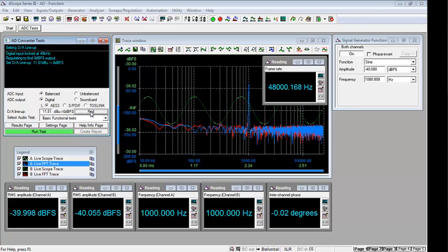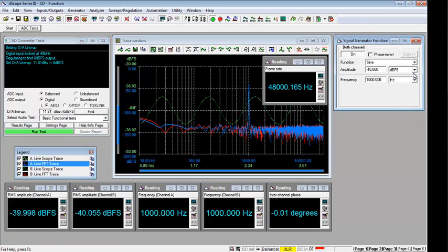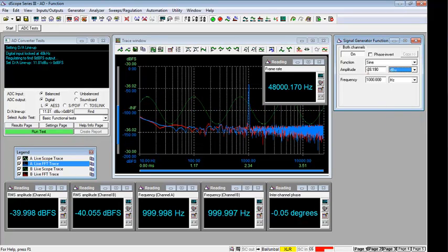First of all, it will ramp up and down the analog signal generator amplitude of the D-Scope measurement system to the point where we reach 0 dB full scale on our digital output of our converter. If for any reason that can't be achieved, and that does happen in some situations, we will run through a second loop looking for the point where the distortion reaches 1%, so the clipping point of our converter. And one of those two conditions will be taken as the maximum analog input level, otherwise known as the DA lineup.